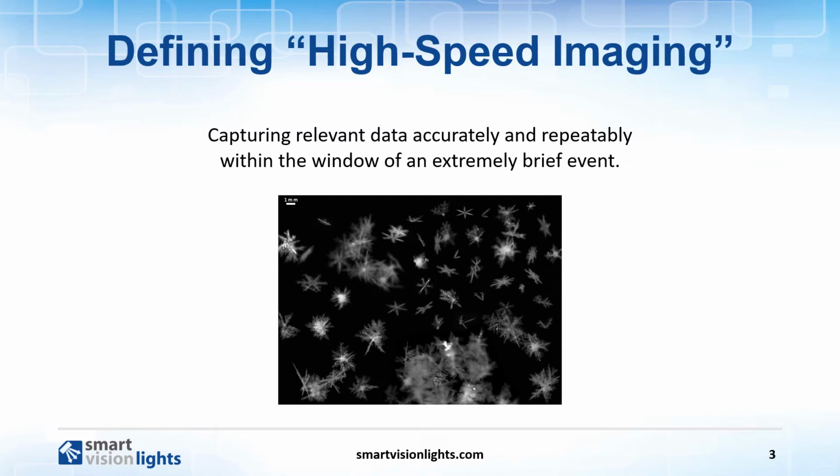Capturing snowflakes requires high magnification and a small field of view to see the minute details. The field of view is about 1 inch here. Yet the system is required to capture snowflake images with winds up to 70 miles an hour. Imagine the speed of a snowflake passing a 1 inch field of view at 70 miles an hour. This requires a shutter speed in single-digit microseconds to freeze the motion and prevent blurring. Saturating a camera image in microseconds requires extremely bright light. In this case, so bright that the light from the LED source within the field of view drowns out the ambient photons from the sunlight in the background.